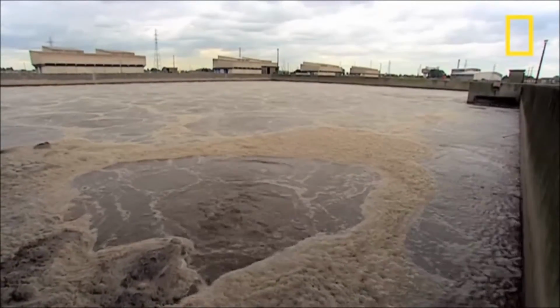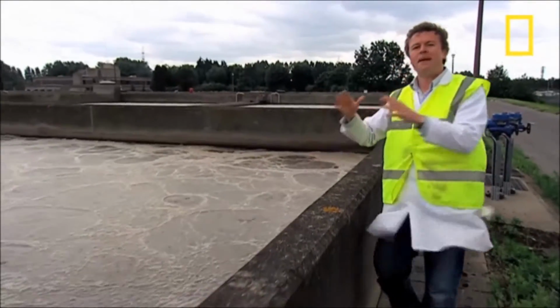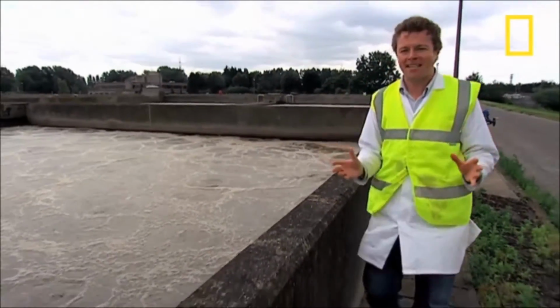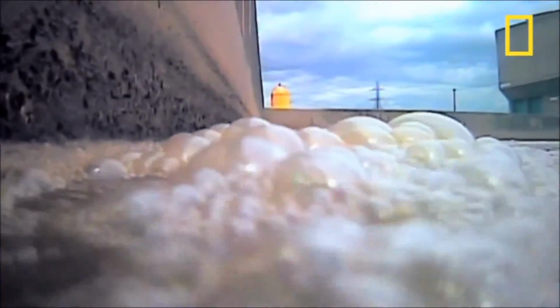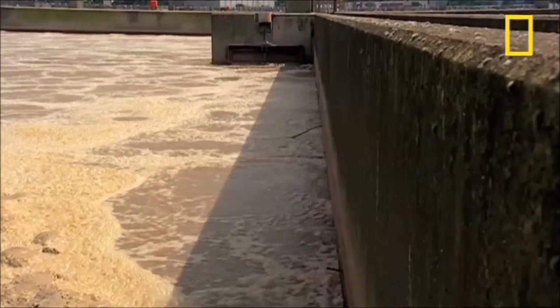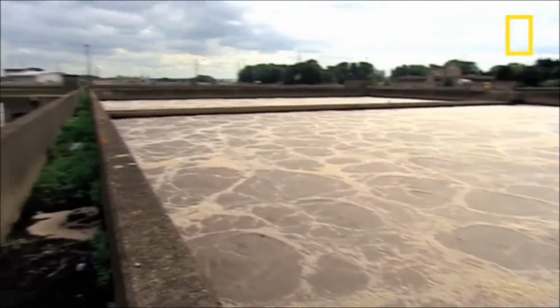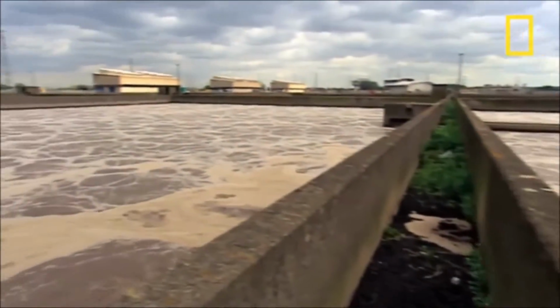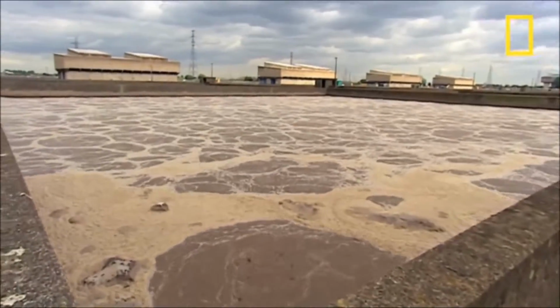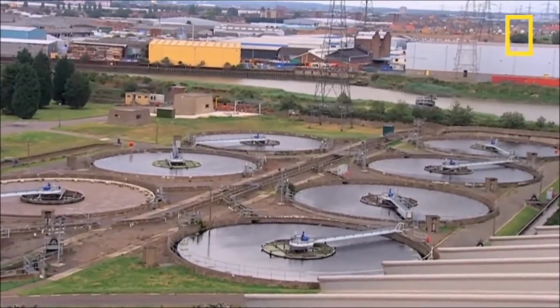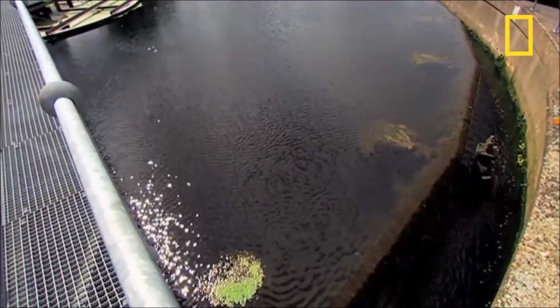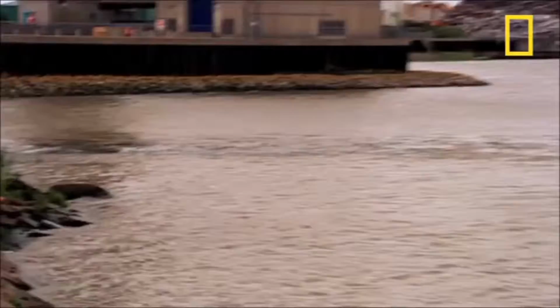And here it is. In these tanks, the sewage is mixed in with billions upon billions of bacteria, so all the dissolved materials that still remain can be biodegraded. And pumping air from below at very high pressures causes the sewage to be saturated with dissolved oxygen, and this accelerates the biological breakdown. It's brilliant. Finally, the treated effluent is tested to ensure it's clean enough to go back into the Thames.